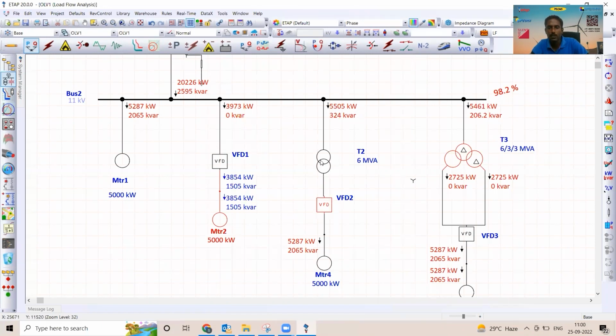Why do we use transformers? Some variable frequency drives, like a 6 pulse direct drive, do not need a transformer, but normal 2-winding transformers might be needed for a 6 pulse variable frequency drive to handle the harmonics, the unbalance, for isolation purposes or for EMC requirements. It depends upon how the variable frequency drive is manufactured. You can Google direct drive or 6 pulse and 12 pulse drives to understand.